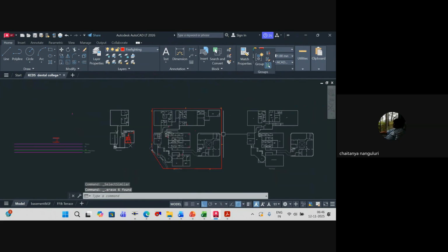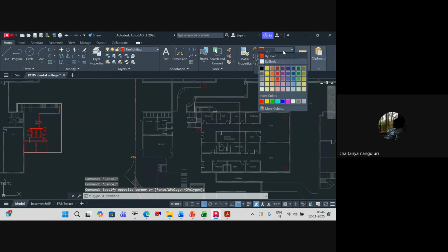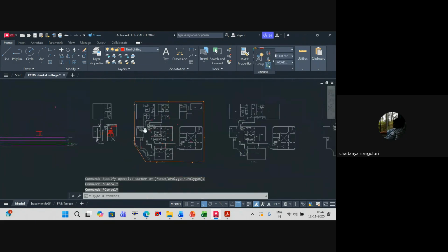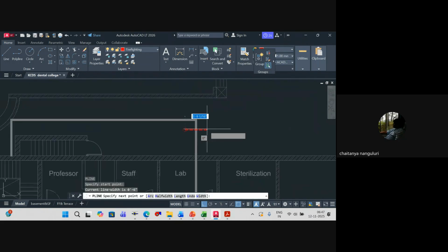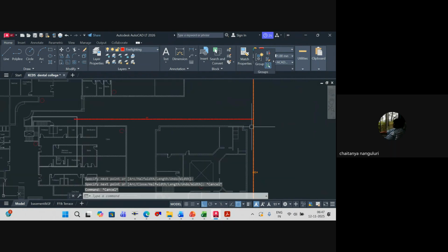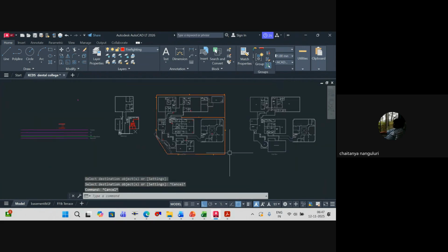So we've got our yard hydrant circuit. I'll make it a different color for ease, an orange color. This is our yard hydrant network. But now from the yard hydrant, I have to connect it to this. You agree? Yes, sir. So we made this particular pipe, which is also 6 inches in diameter. So we've got a pipe running around the building. It could be underground or overhead, depending upon your site conditions. Clear?